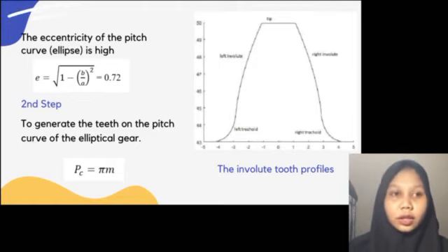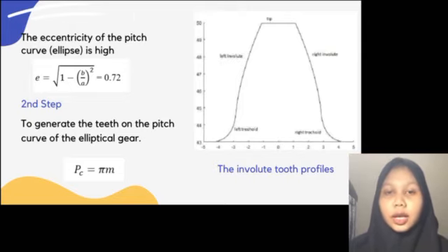This function has the basic inputs rho, m, phi and others, and it gives the tooth and the coordinates of the tooth profile as outputs, for the purpose of generating a text file of the coordinates to be used in generating a 3D elliptical gear in the SolidWorks mechanical design program.